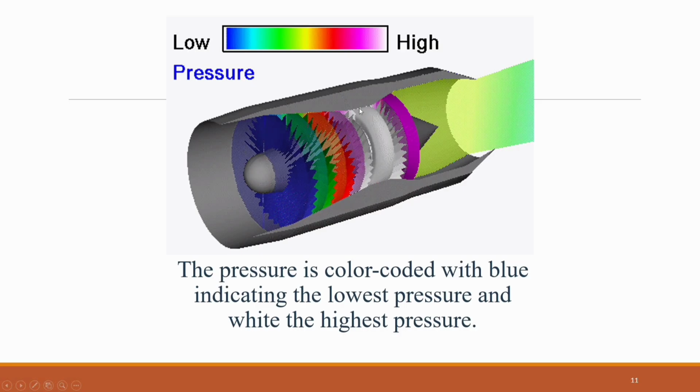The high-pressure air then enters the burner or combustion chamber, where a small amount of fuel is mixed with the air and ignited. Combustion occurs at nearly constant pressure, dramatically increasing the temperature of the airflow and adding energy to the exhaust gases. The hot exhaust then flows into the turbine, which extracts energy from the high-energy gases to drive the compressor via a central shaft. While some pressure is lost during this process, the gas entering the nozzle still has a higher pressure than the free-stream air.